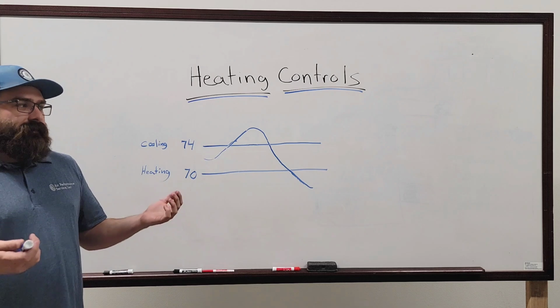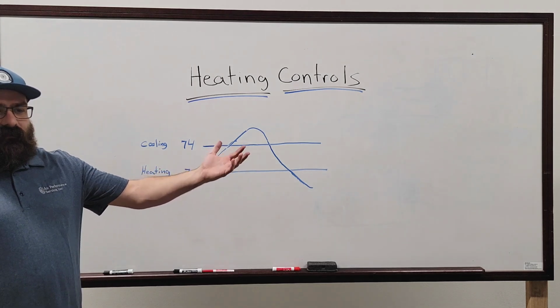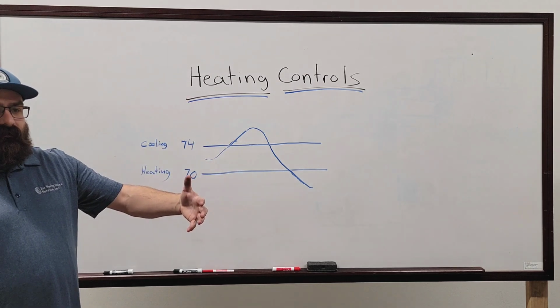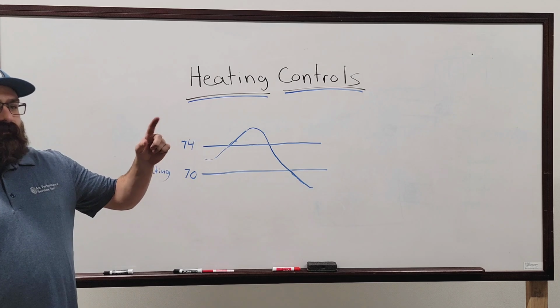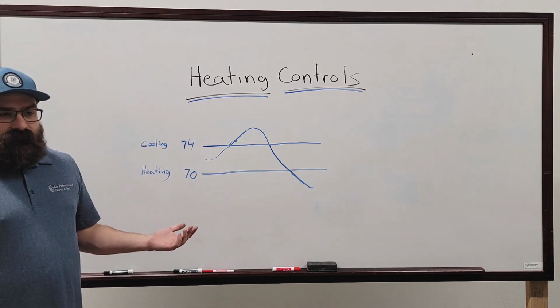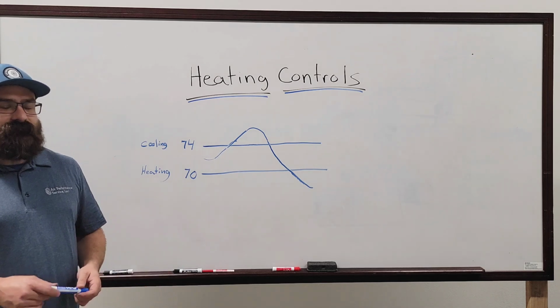And in reality, there's only like 5 kinds of VAV boxes. So you can build a program with 5 optional things, right? And you can make it toggle between what functions it does. There's no point to rewrite the book. Like, it's done. Like, I've been using this.